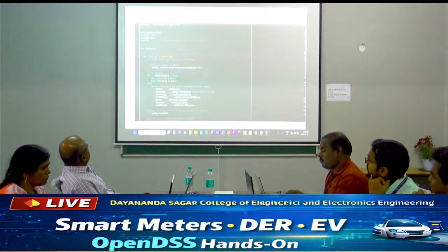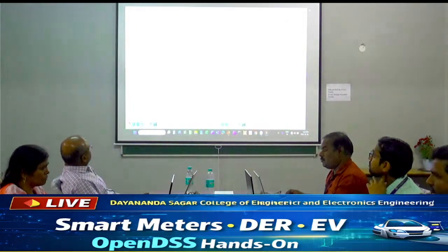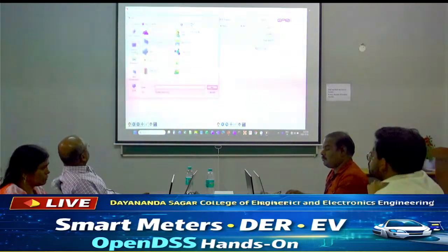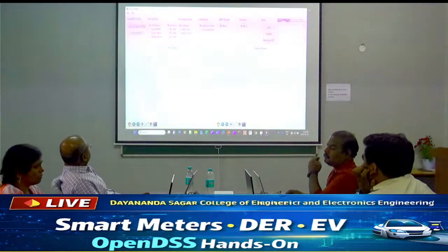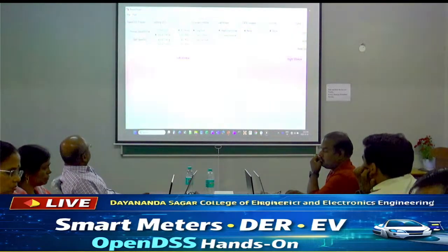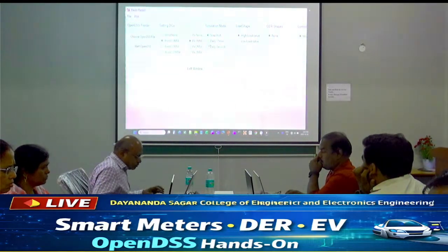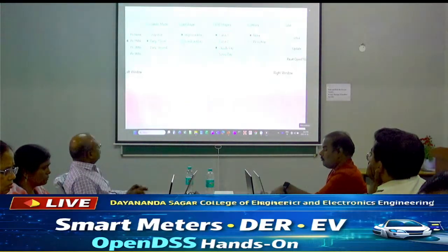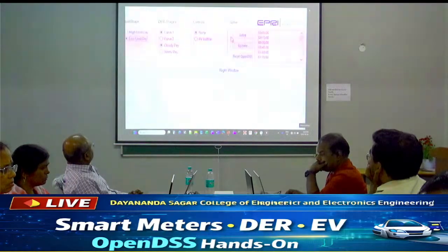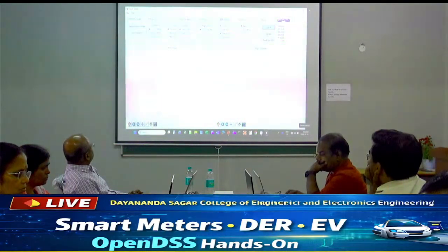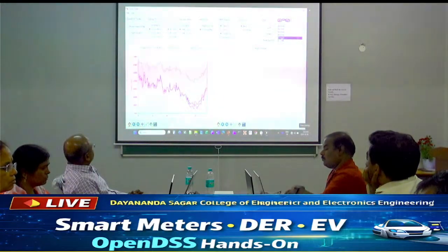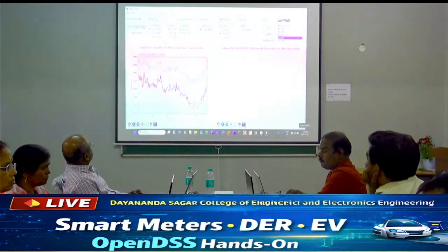Another useful tool is to create an interface for OpenDSS. Here I have an example to show the simulation results. I choose a DSS file which has a solution network, and I can place some bars that show the system objects inside. I can also select the simulation and curves for the loads in the distribution system. So with this setting, we can plot the voltage per bar and see it in the left window. And for example, we can choose a specific time and plot the grid profile at that specific time.